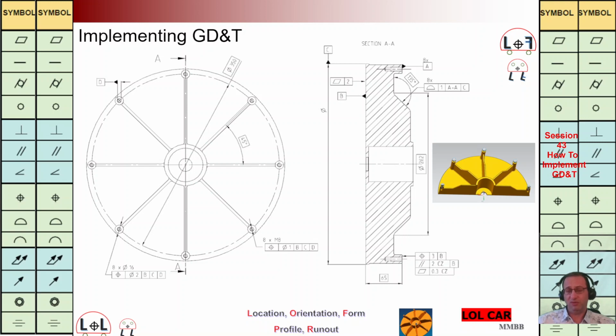That's why we are going to define it as A. In order to qualify or machine this surface as A, I need to use a big surface to fix my component, and my component should sit on this surface. That's why I'm going to define B as well here as a secondary reference plane, and A and B are connected, dependent on each other somehow.